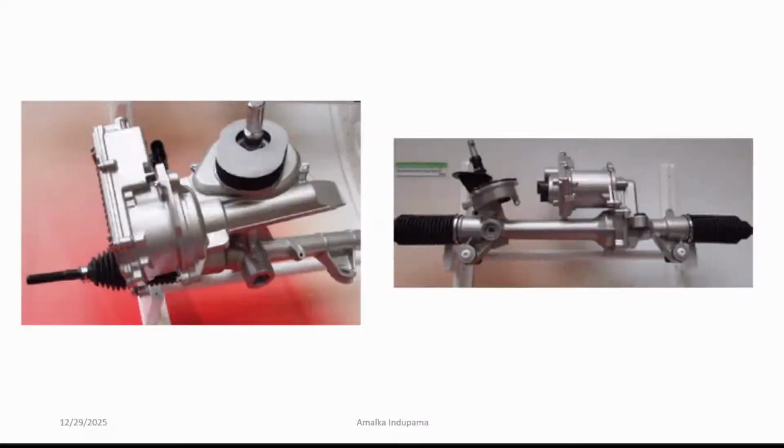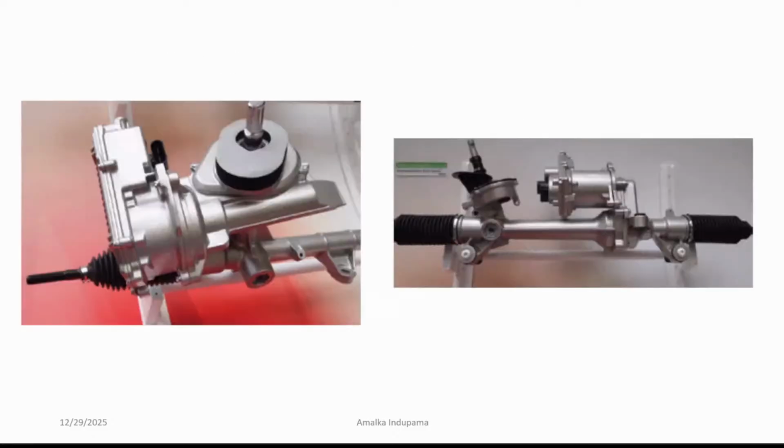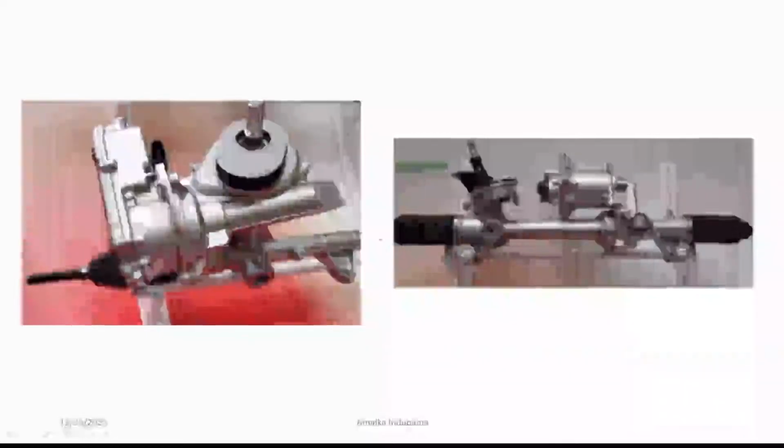Older vehicles can now have power steering with EPS. Replicating a hydraulic power steering system is not as easy as EPS. The best method is using EPS. It is not generally recommended, but EPS can be installed in any kind of vehicle by simply connecting this gear motor along with the feedback system to the steering column.